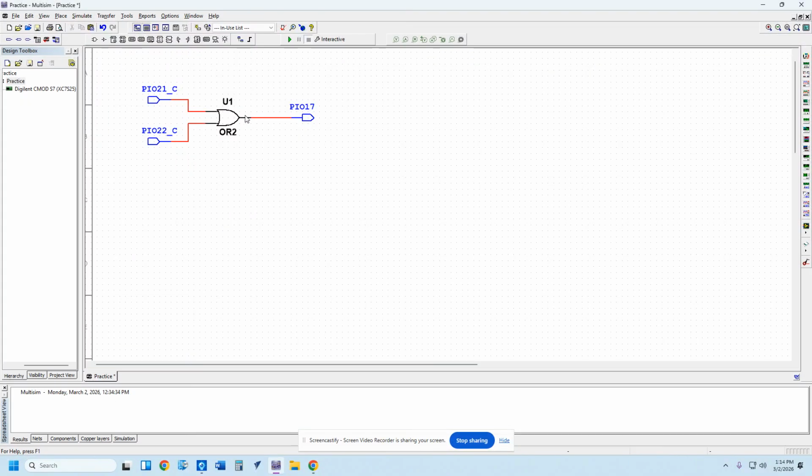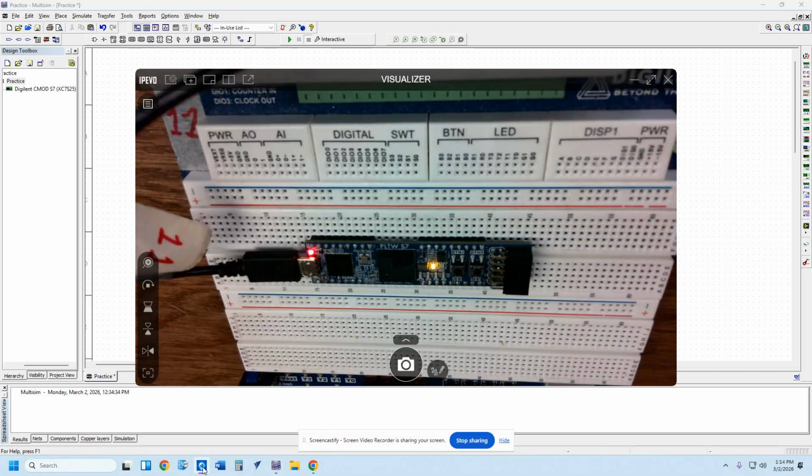But you do need to upload it, so this is the next step. Of course, in order for this to successfully upload, you've got to have the USB cord plugged in, and you should have it powered up, and the ready light should be on. If those two things aren't happening, we've got problems. We've got to figure out what the situation is with that. But before we upload it, just to make sure that the microchip is happy, because sometimes it gets a little weird when you plug stuff into it, we're going to hook up the wires ahead of time.